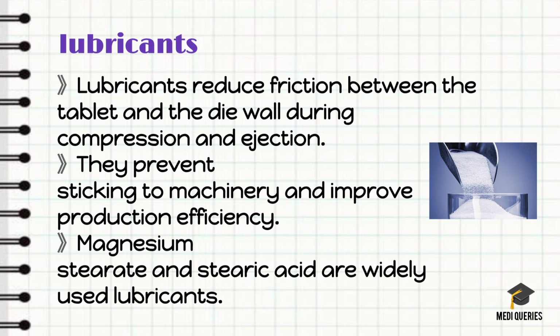Lubricants are typically added at the final stage of blending to ensure even distribution. They must be used carefully to avoid affecting tablet hardness or drug release. Hydrophobic lubricants like magnesium stearate require a low concentration, usually below 1%. A proper lubricant ensures smooth manufacturing and better tablet finishing.